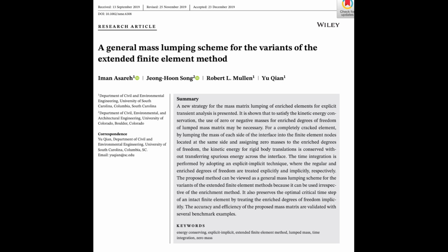Easily. Finally, they simulated a compact compression specimen test, figures 13 to 16, Table 1. This showed the method worked with different variations of XFEM. They mentioned SX and NX specifically. So confirming that generality you mentioned? Yes, and showing it could handle complex, curving crack paths, even in a non-uniform mesh, which is more realistic for complex parts. They did note some minor differences in the crack length history between the SX and NX variations, which is more of an internal XFEM detail. So it seems robust across different setups.